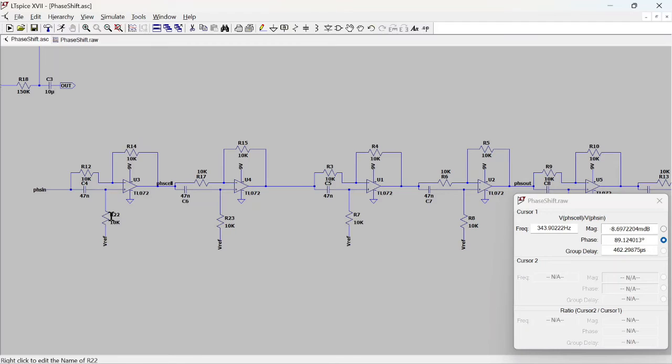So if we lower this, we can't increase this because the JFET will be in parallel. So even if the JFET appears as higher resistance, it will be way higher, and at maximum resistance, when it is turned off, the maximum resistance will be 10K.